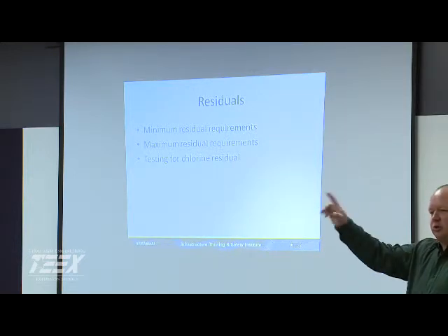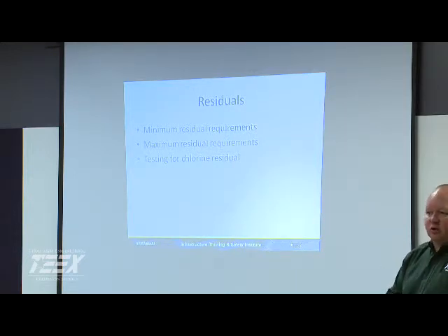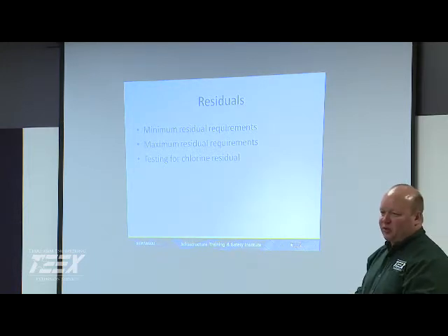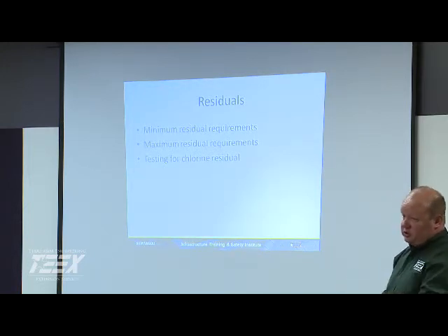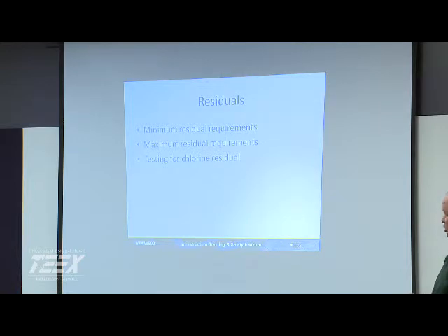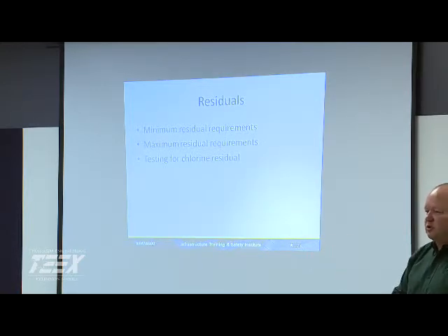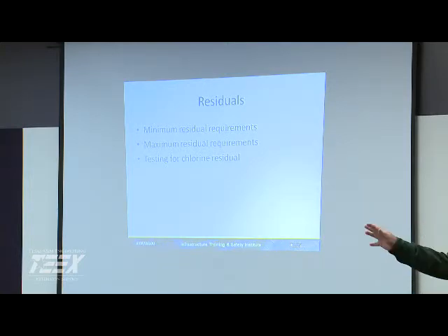You're using colorimetric? Is it like a CL17? Yeah. Okay. They're a great system, requires some upkeep, some preventative maintenance and corrective maintenance when they go bad, but that's a good system, like the CL17. They're doing some now with oxidation reduction potential, ORP systems. Kind of interesting how they're moving away from some chemical additives, but there are pros and cons with it all. Y'all are testing what, once a day for your residual? What are you using? Do you have a handheld?